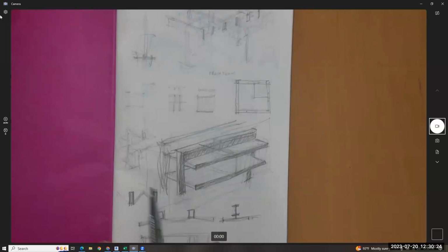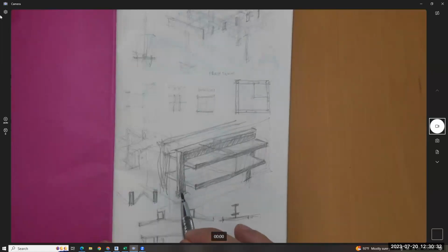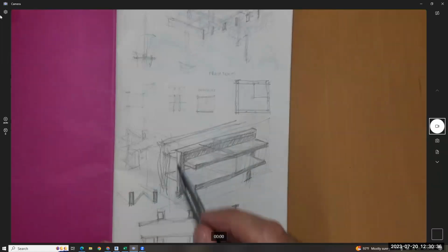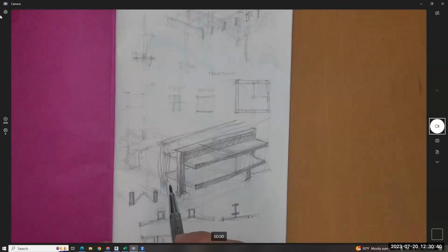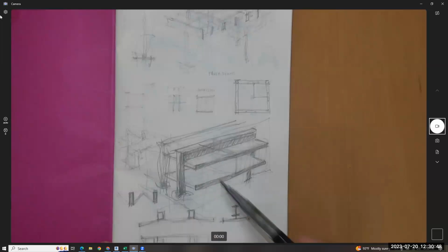You could be a little fancier this way and highlight this. And this is where the idea of editing and telling you a story comes in, I want you to show me what's happening. I might highlight this one a certain color and write it this way. And then I might highlight this footing or outline this footing and say moment connection, resisting in this direction, because those are like the flagpole things, right? That's what's kind of stopping it in that way.